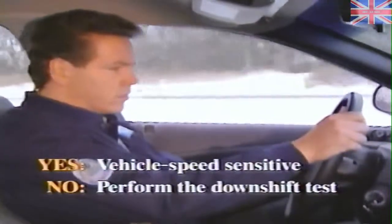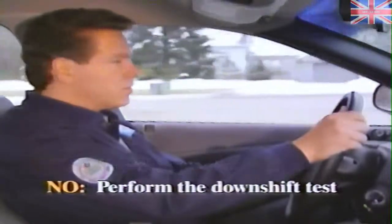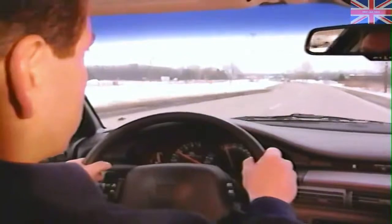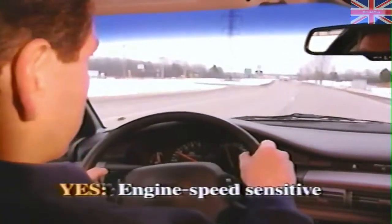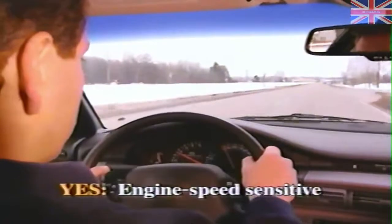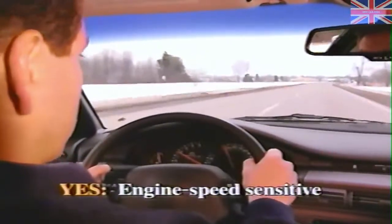If the noise or vibration does not occur during the neutral coast down test, decelerate and safely downshift to the next lower gear. Then operate the vehicle at the previous engine RPM. If the problem returns, the noise or vibration is engine speed sensitive, and the engine or torque converter are the most probable locations of the problem. You may repeat this test in still lower gears and in neutral to confirm your results.